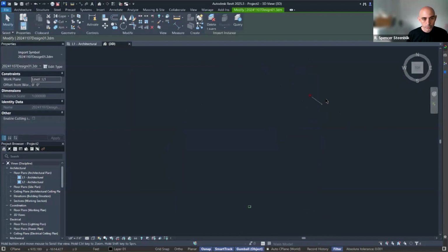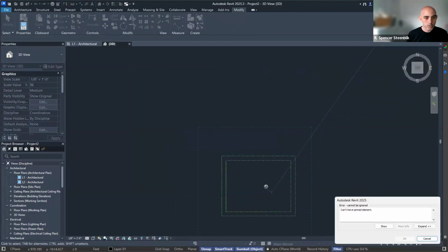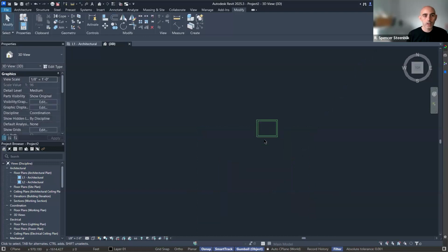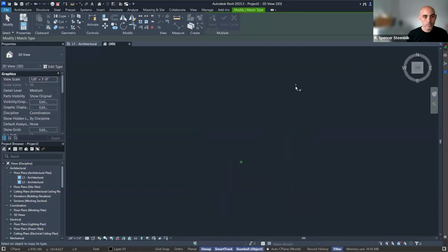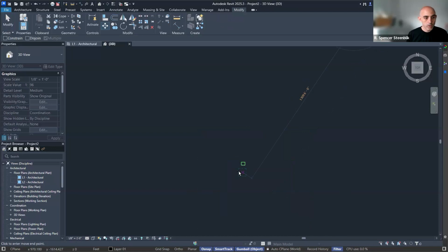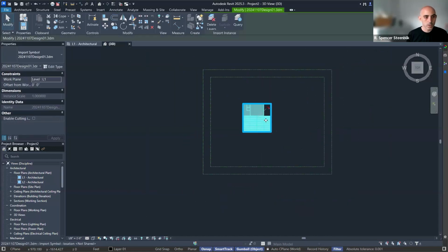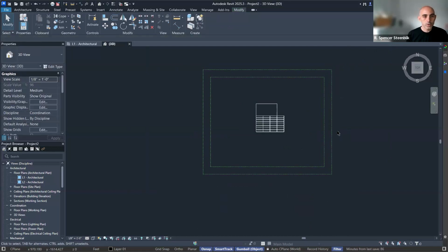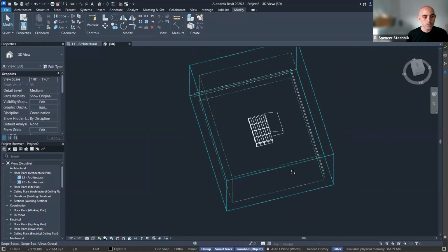And we can just move that object by typing MV to move. And then we can move it to this existing box. Oh, it's pinned. So we got to go back and unpin that element. Unpin it. Now we can move it. MV. A lot of the quirks of Revit have been worked out, and it's so much easier now than it used to be, which is nice. So now we have that, and we can scroll out of that 2D view, zoom extents, ZE on the keyboard.